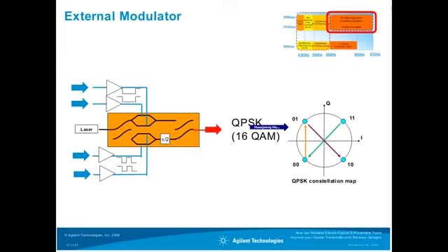For this external modulator, it's also important that you look at the transmission characteristics of the individual driver amplifiers to the modulator, and that they are well matched, well matched in amplitude and also in phase.